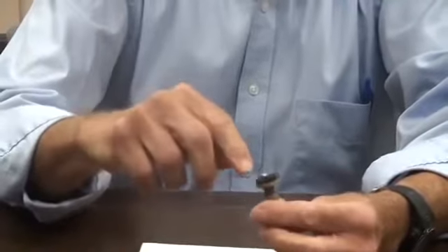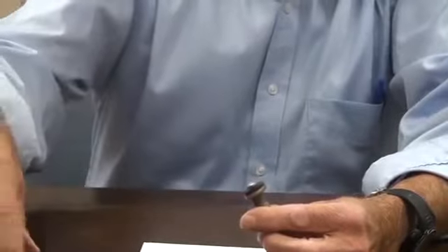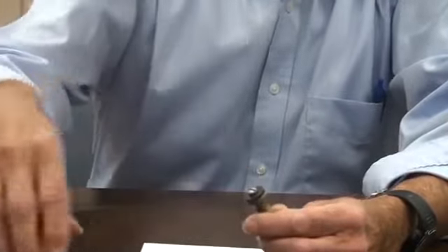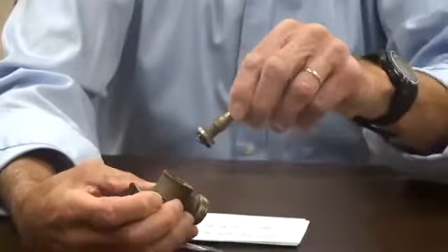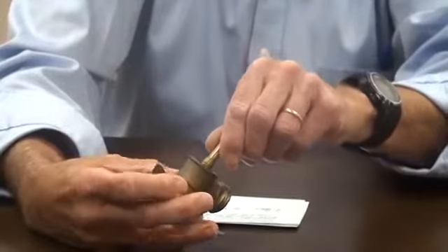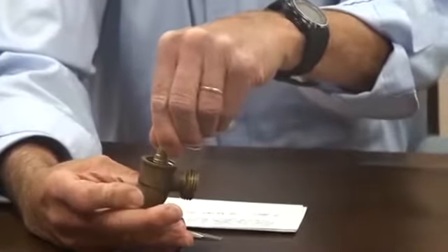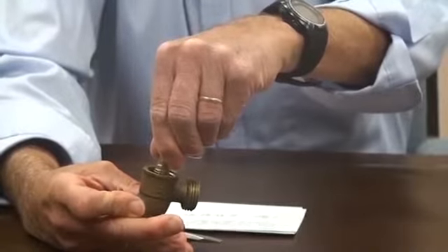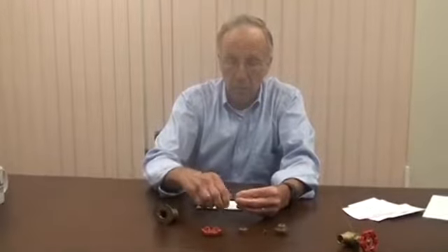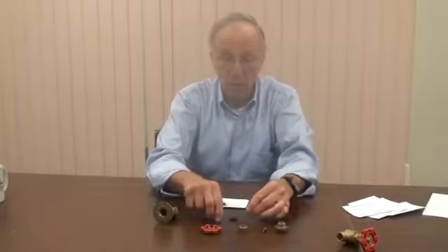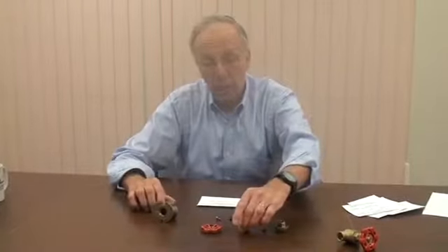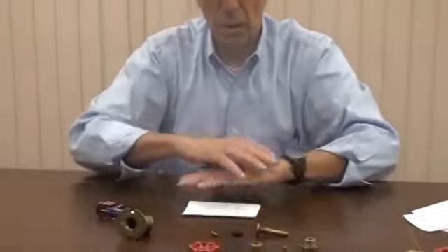So what happens in the functionality of the faucet is this rubber, called a faucet washer, not surprisingly, when you screw the valve down, it bears against the machined portion of the base, and that's how you seal off the water flow to the hose. So we can quickly disassemble it, and it's made so that the faucet washer can be replaced if it wears out, and also if I were to take out the washer inside this piece, which seals along the stem, that's also replaceable.